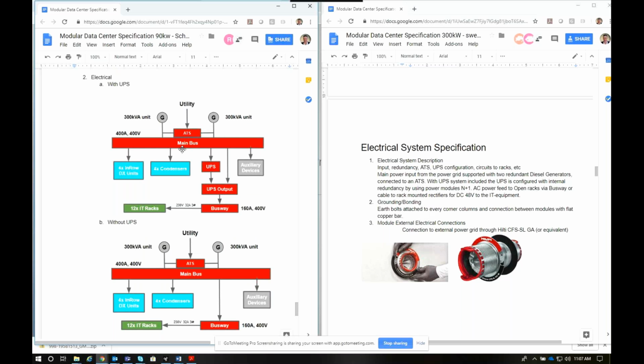And then this particular design has 2 gen sets. I don't know if you guys discussed that was something we did specifically for the Uptime Tier 2 requirements, but a lot of customers at that smaller solution wouldn't be using 2 gen sets. So you might want to put something like optional. Yeah, that's a good point. Tier 2. You still need to remove those extra lines that are between your generators and the main bus.